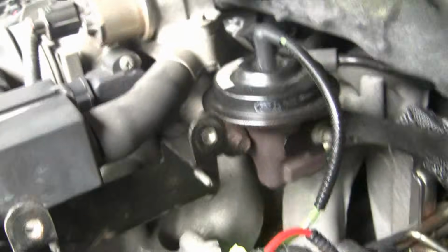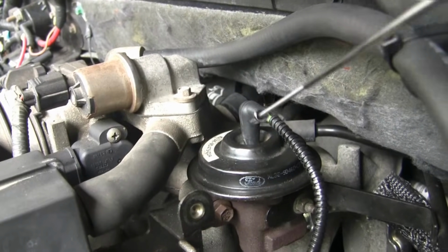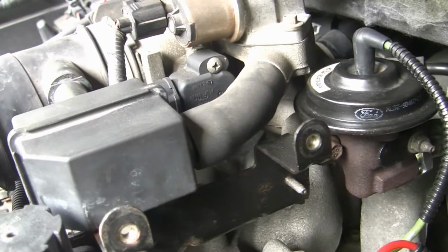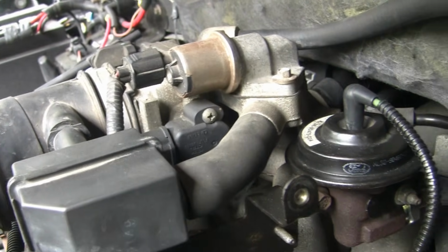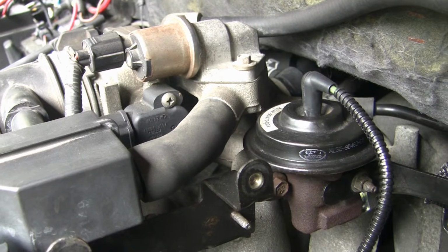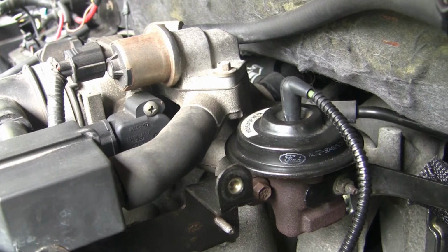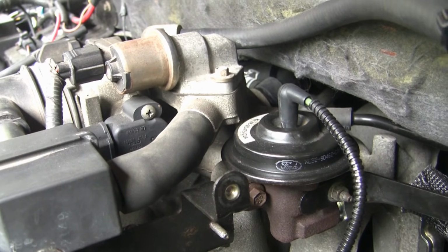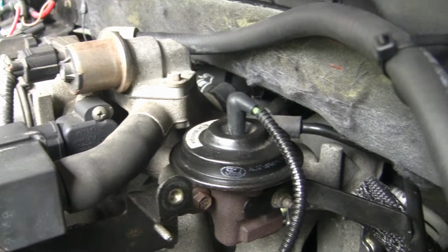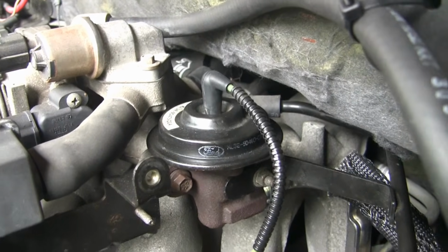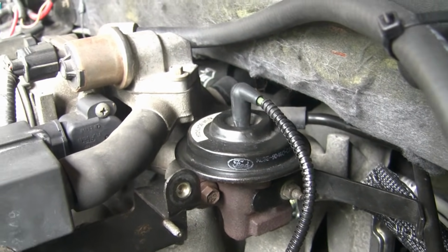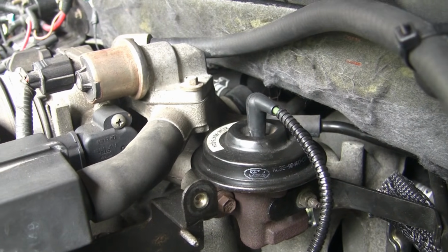Anyway, I kept telling him, when you apply vacuum to this guy, it makes the engine run rough, but it doesn't stall it. Therefore, my assumption is that the problem is indeed in the throttle body being clogged. But in any regards, where we're at right now with this engine, I talked to another mechanic who I trust a little bit more, and he agrees with my assessment. He says, although it could also be the EGR valve itself, it's not completely opening when you apply the vacuum to it. So we'll see what he has to say, and then I'll give you an update on this.